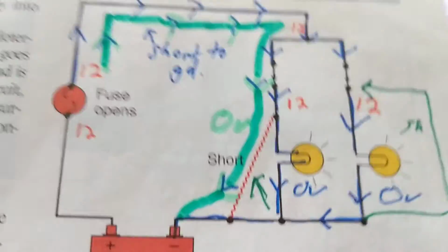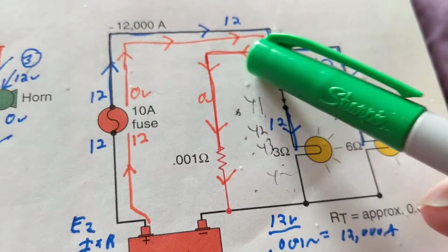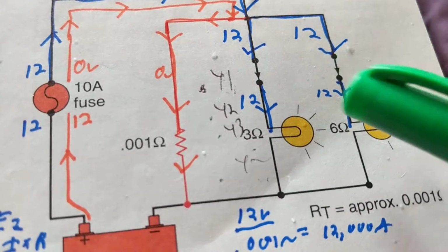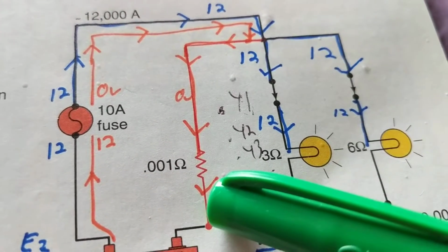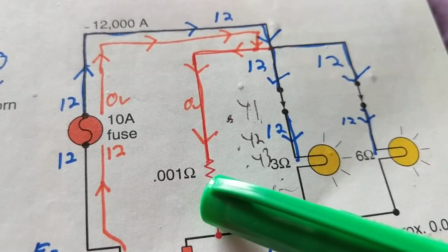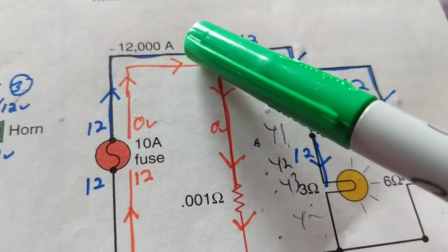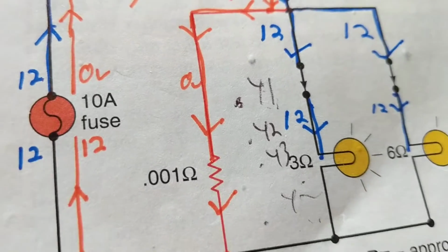That's how we have to go about it. Okay? Same idea over here. Now, like we said, same thing over here. Here's a resistor, very low resistance. We put it across. Guess what? Now, instead of 3 ohms over here to 6 ohms over here, now we have 0 ohms. When you have 0 ohms, with Ohm's law, guess how much the current is? Yep, 12,000 amps. What battery in the world can deliver 12,000 amps?